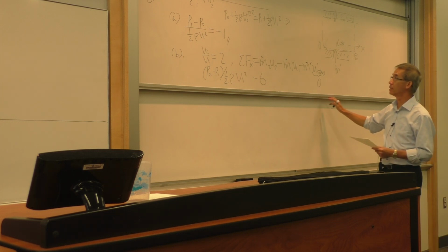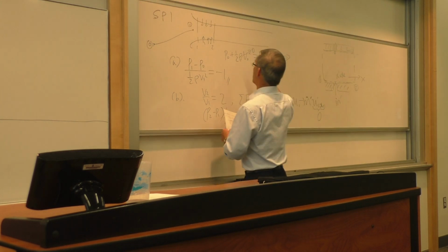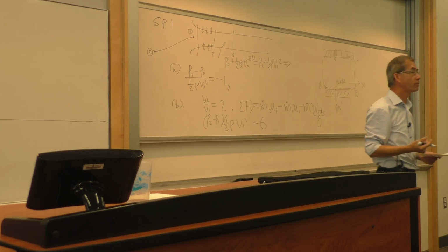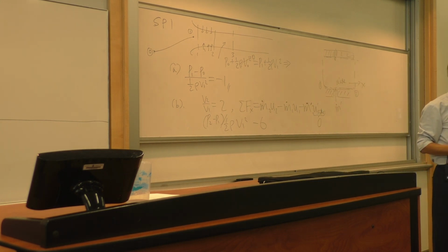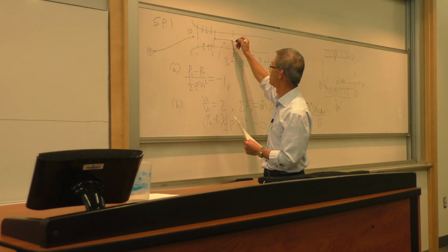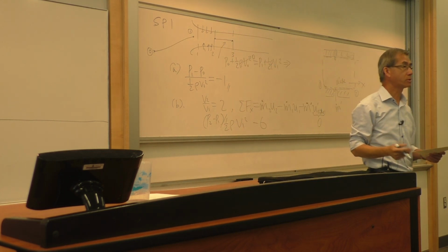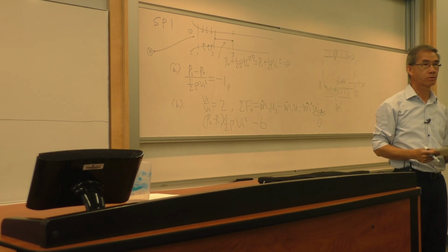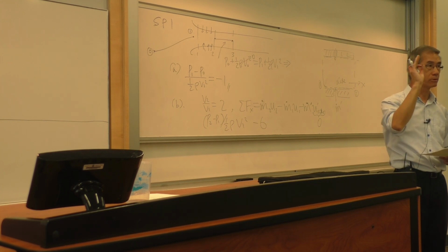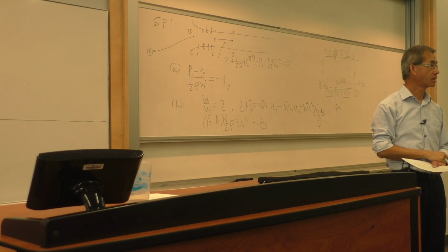Okay, the next part, and then I will stop at that, is simply confusing you by saying I'm adding a small amount of heat into the flow, but not enough to change the density. Now energy is being added because of the heating. Can you still use Bernoulli? Yes. And no bearing on the Bernoulli usage whatsoever. So I would just simply follow the streamline along the center and bang. The conclusion is no change. No change in pressure because there's not enough heating to change the density, and Bernoulli says no pressure change. Do you get it? Questions?